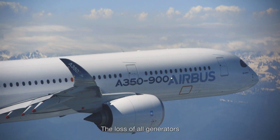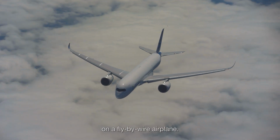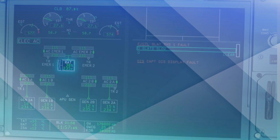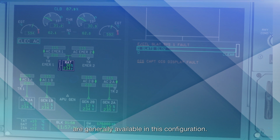The loss of all generators is obviously a critical situation on a fly-by-wire airplane. In these circumstances, electricity is usually produced by a ram air turbine below the wing or the fuselage, driving a small generator. 2 flight control computers are generally available in this configuration.